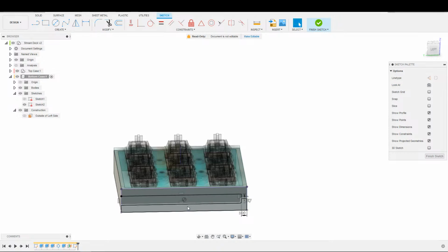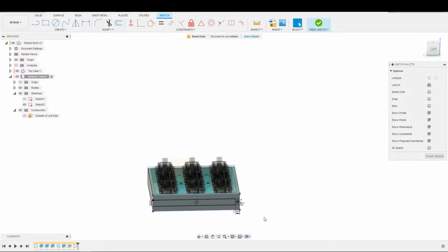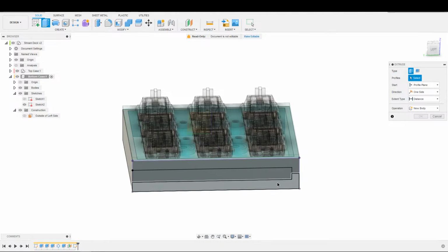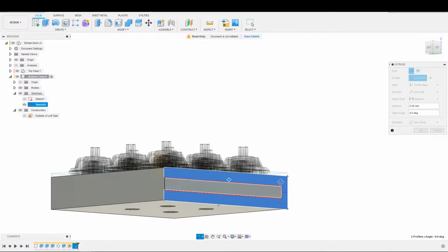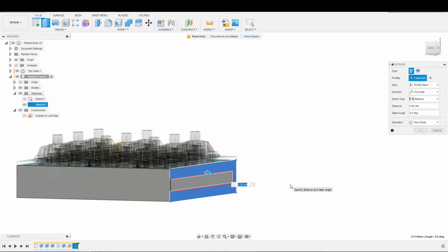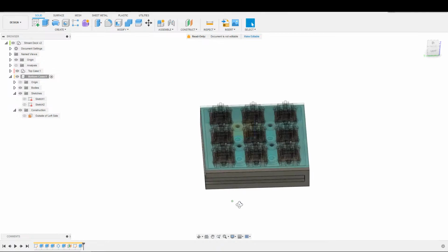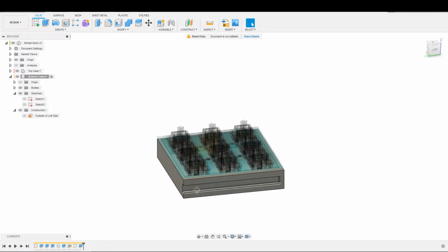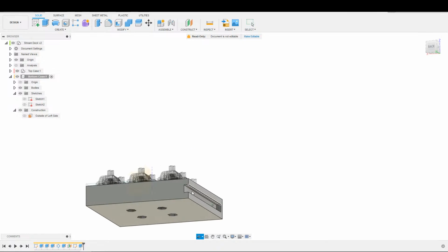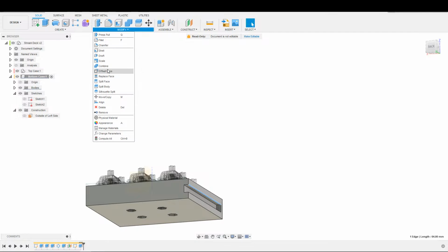We should be good. So the only issue that arises doing it this way, putting this slot in here, well, there's 2 issues that arise putting this slot in here. Let me just extrude it first, and then I will elucidate. I guess 3 millimeters is fine. It doesn't have to hold, it's not holding much weight. First off is that this is an overhang right here, and we don't want to relieve this overhang. Let me just relieve this overhang really quick, for example.